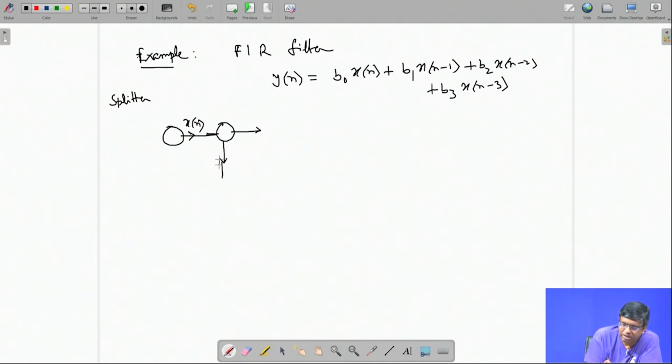Then by the side of it is an edge, where I can have a multiplier or a delay or both. So, I write b0. Then I have another node. Normally, these two can be different nodes, but we just indicate them by bubbles or circles. But then one can ask how do I know what kind of node it is. Just so you are not confused, I put a plus here to indicate it is an adder node.